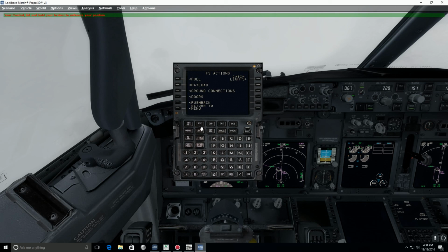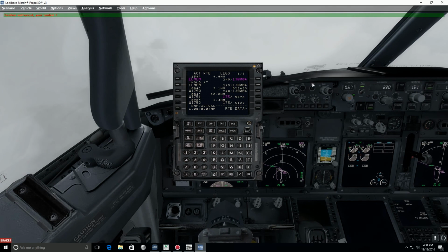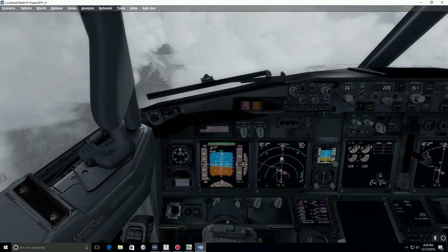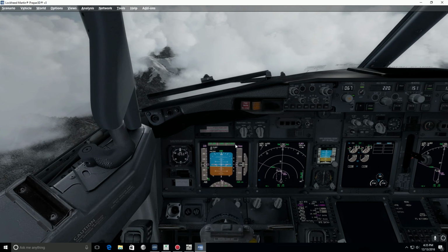Good. So now we have our FMC going to LMM and join the hold, as we can see here. So we're ready to fly and prepare the aircraft. Alright, so LNAV is armed. I hold my brake to take control, and now the position is on freeze, and we can see that the aircraft is actually now flying toward LMM to join the holding.